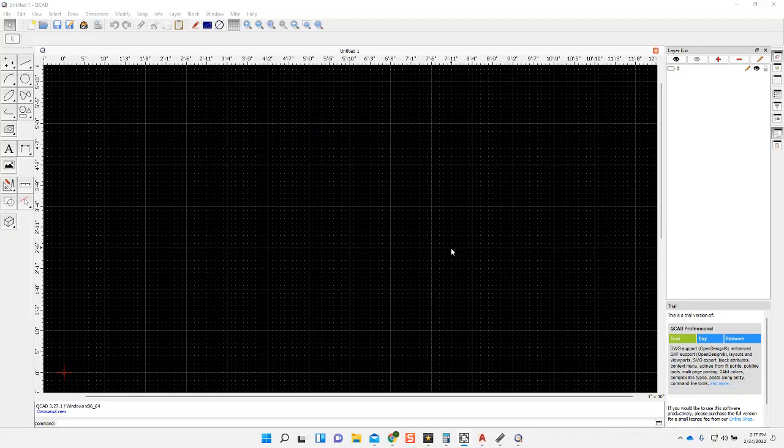In this section, we'll go over the different options for CAD. Your CAD file is your drawing file that you'll use just before creating your toolpath in SheetCam. There are many different options of CAD software to use. Programs like SolidWorks, Fusion 360, AutoCAD, QCAD, and so on. They all relatively do the same thing with different functions and accessibility. Your table will be loaded with QCAD. You can use any program that you'd like, just as long as you create a DXF.